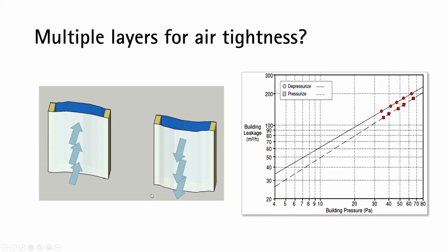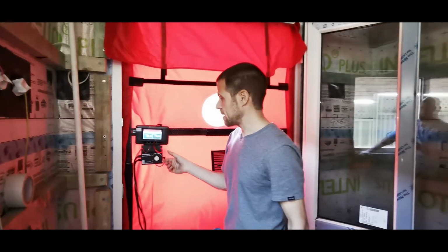When you have an interior air barrier product or system, often the depressurization mode is worse than the pressurization mode. So when you're pressurizing, on the left graphic, you're pushing that interior air barrier closed, you're pushing it tight, it seals tighter. Under depressurization, you suck all those leaks open, they lift away from their staples and more air leaks out. So that's how you can use a blower door test very simply to help you diagnose some problems.